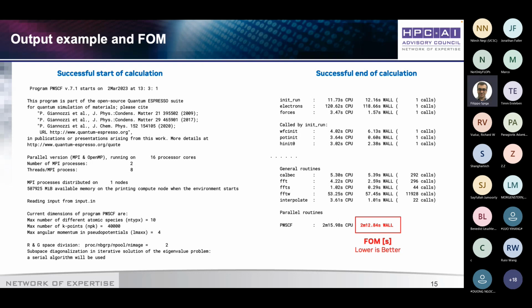Essentially the CPU time tells you if you're going multi-threading, whether you're actually using all the cores all the time, 100%. So there are 2 scenarios. The CPU time is in between your wall time and the multiple of the wall time times the number of OpenMP threads that you're using. And that's okay if it stays in between.